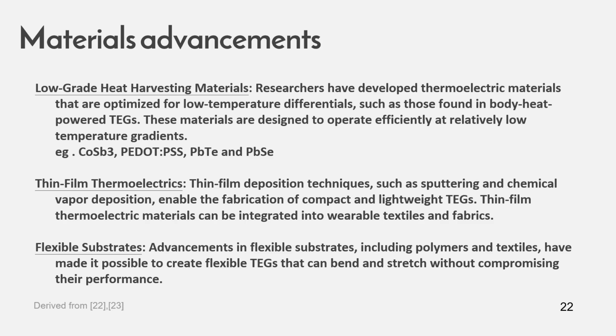And the fifth one is thin film thermoelectrics. Thin film deposition techniques such as sputtering, it's a physical vapor deposition technique, and chemical vapor deposition technique enable the fabrication of compact and lightweight TGs. Thin film thermoelectric materials can be integrated into wearable textiles and fabrics. And the last one is flexible substrates. Advancements in flexible substrates including polymers and textiles have made it possible to create flexible TGs that can bend and stretch without compromising their performance.